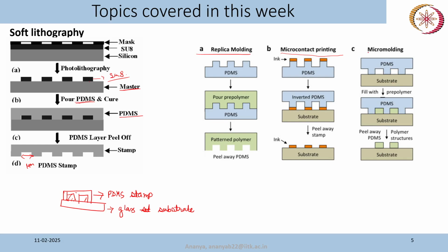Okay, so these are different types of techniques. The advantage of soft lithography, as I mentioned, is that it is relatively easy and low cost. However, there are certain trade-offs also. You cannot make very small dimensions with this lithography, and you have to be very careful while you peel off